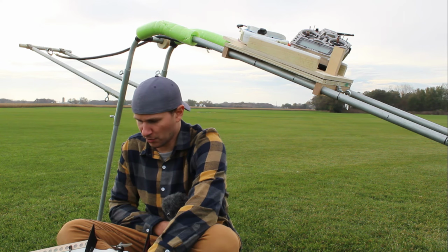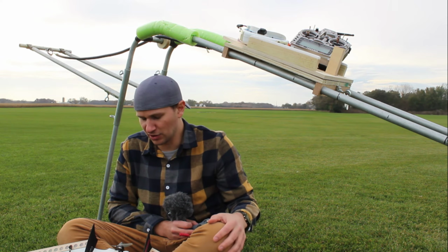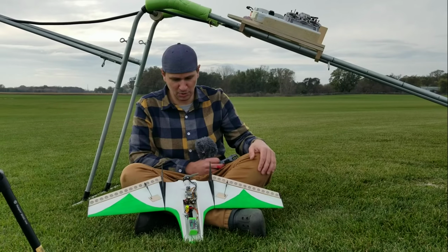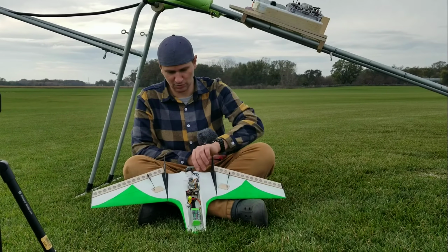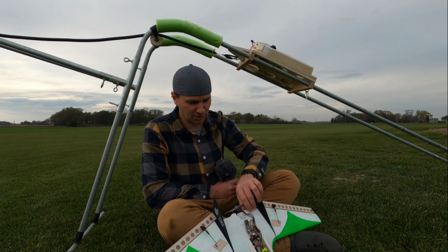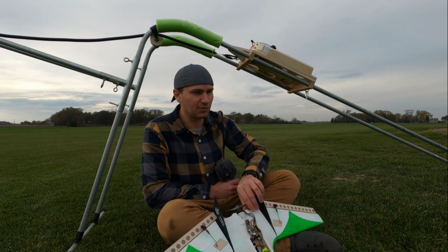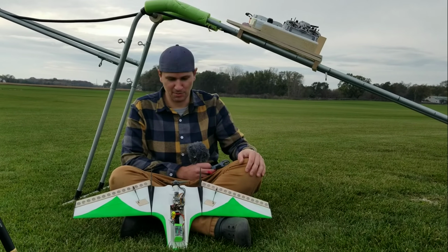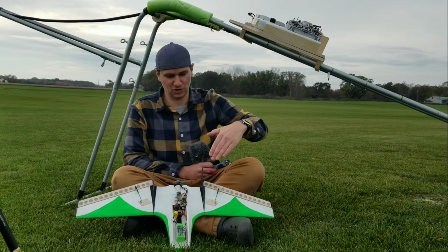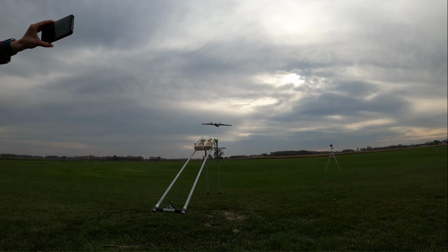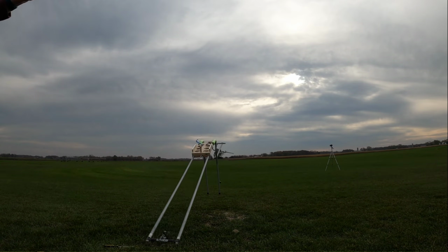Another thing that did not help was the flight controller. I thought I had done a thorough horizon calibration on this, but in hindsight I probably should have checked one more time after I reflashed Mission Planner onto it. In stabilized mode, the plane was definitely pitching down. If you look back at the footage from the launch, I'm pretty sure that's the reason the plane pitched straight down right after the launch. Once I had it trimmed in manual mode, it was actually pretty fun to fly.